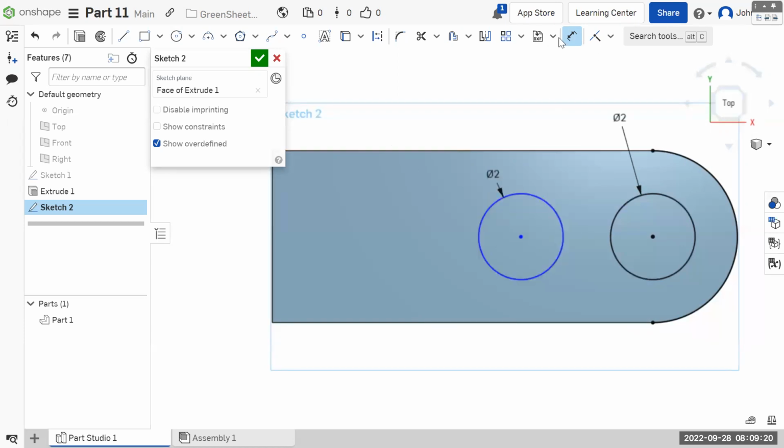And then in order to make sure they're the correct distance apart, which was 3, with the dimension tool, I can dimension the distance between the center points, which I don't know why it's not clicking there. Okay, so the more foolproof method would be to just, once you have your first circle that snaps to here, draw a line from here, make sure it snaps to horizontal, and then dimension that line. That will give you something solid to connect to with our other circle.